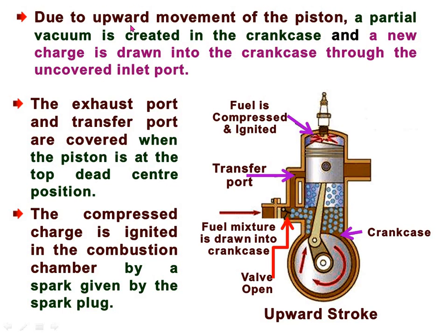Due to the upward movement of the piston, a partial vacuum is created in the crankcase and the new charge is drawn into the crankcase through the uncovered inlet port. See, the piston is moving upward, so at that time the inlet port is uncovered. It is open.